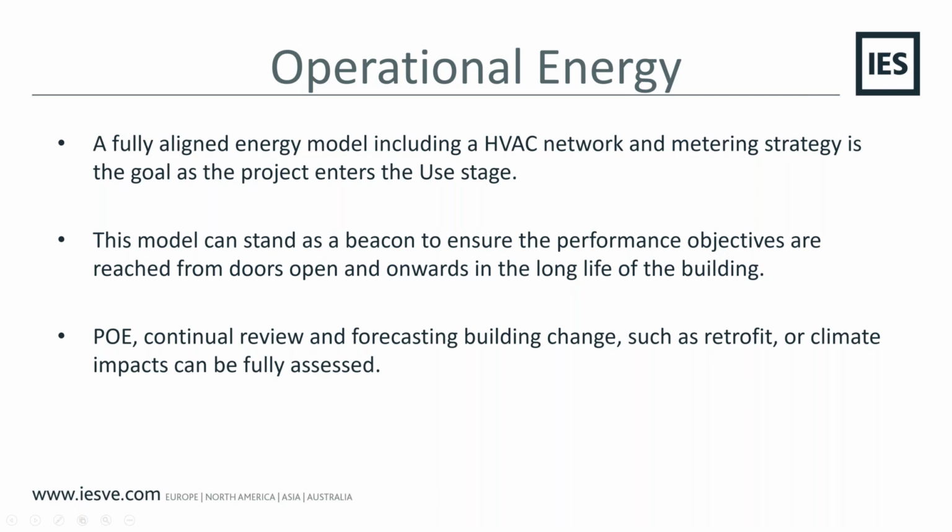Now, when we move from the design stage, our goal to reach and assess the operational energy is to have a fully aligned energy model with an HVAC network, as Michael described, and also a metering strategy, as Phil quickly noted earlier on, that is in line with what the BMS and metering strategy was in place through the design, so that both are synced together, and that way we can take data from the operational building into our operational model.